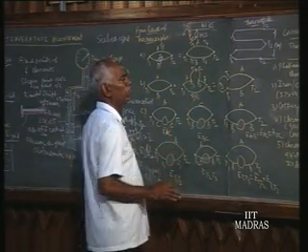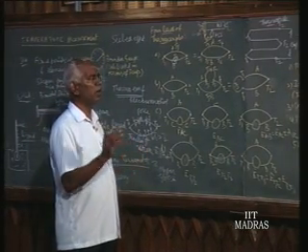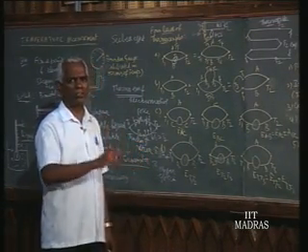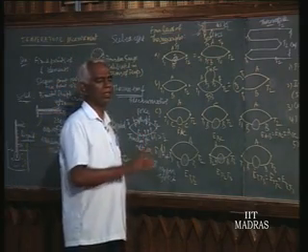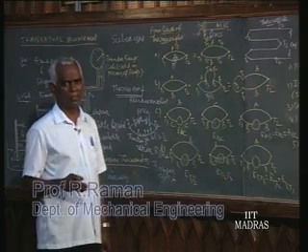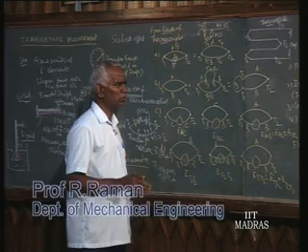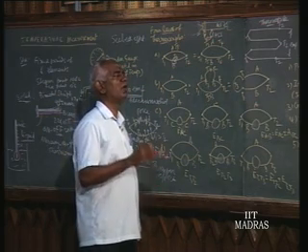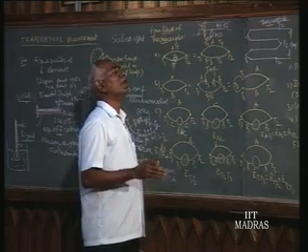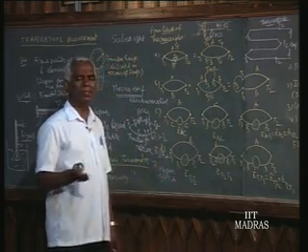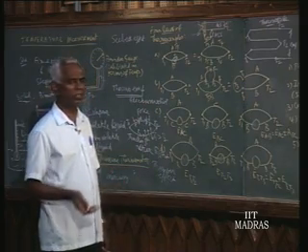Platinum is one material, and all other materials each time are taken with the platinum, one thermocouple is made, and that calibration, what is EMF developed under different temperatures, the cold junction temperature being 0 degree centigrade, ice point. With the cold junction temperature as ice point, all elements are calibrated with the platinum. That chart is already available. And if we want to combine any two elements, then from this calibrated chart we can easily obtain the characteristic without doing actually the full calibration.